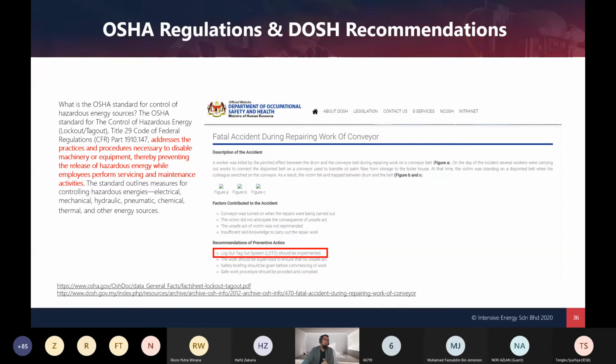But in the industry code of practice for confined space, they mention positive isolation, but they did not mention lockout tagout. Of course, they say install blinds, reverse spade, but they did not mention lockout tagout. So for lockout tagout, as per my knowledge, there's no specific guideline. If you found one, please let me know.